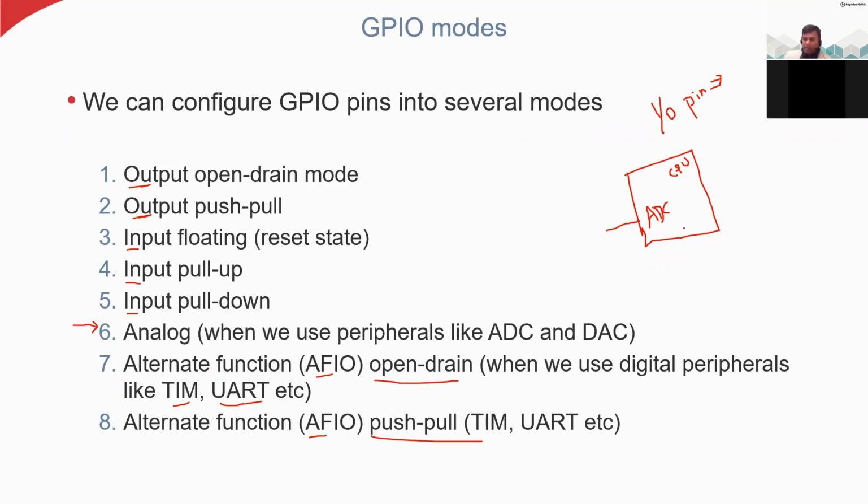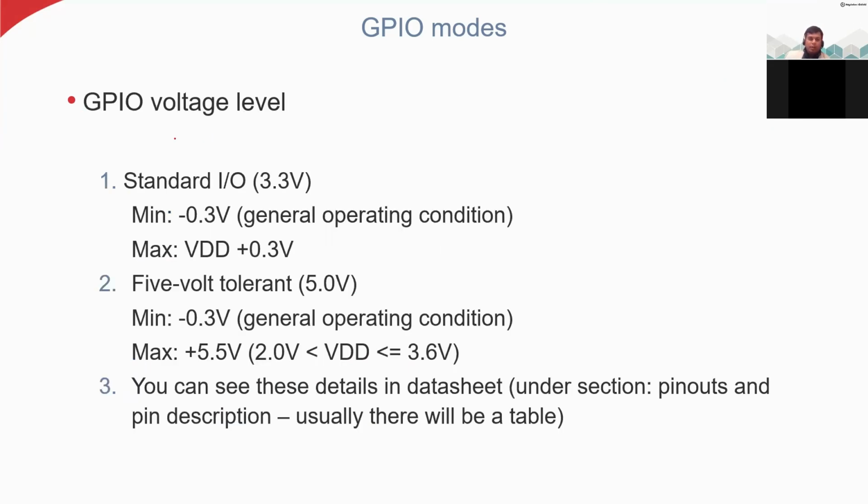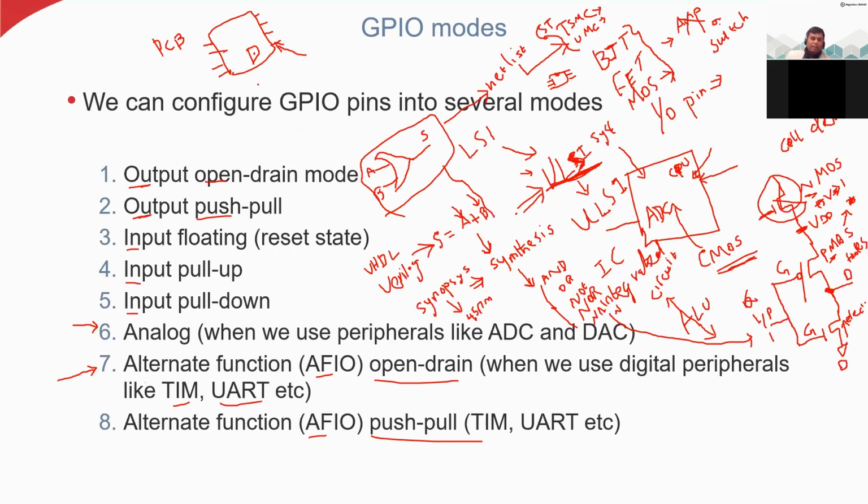Of course, everything is happening inside the microcontroller, but it will be interesting for you to understand the concept of open drain and push pull mode. Inside the chip, we are not depending upon a single high voltage level. Nowadays, we have multi-voltage systems inside the microcontroller. The high voltage, which I mention here, is VDD. It doesn't need to be only plus 5 volt. It can be dual voltages. It can be plus 5, plus 3.3, or any other voltage based on the system designer who is writing this program.